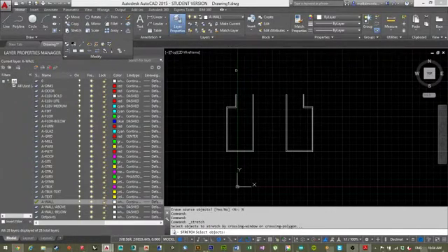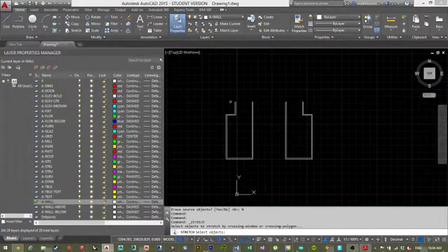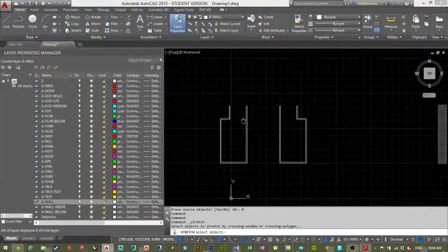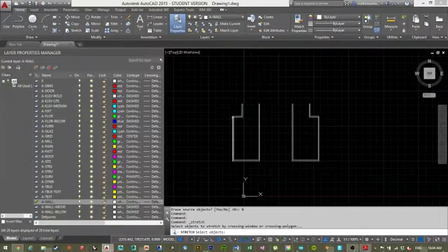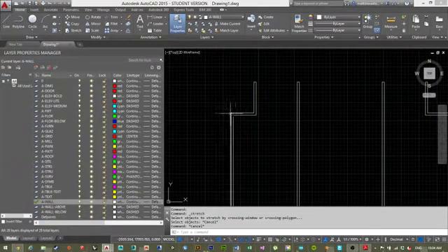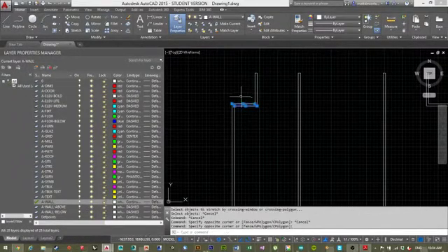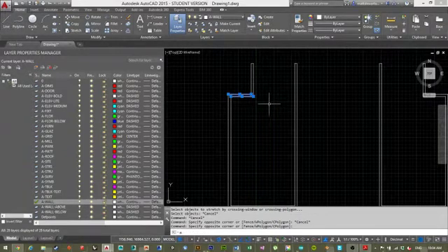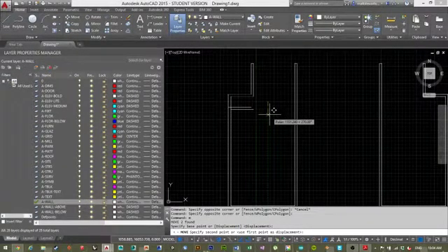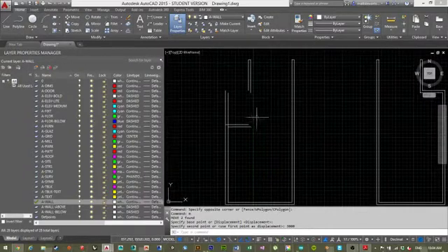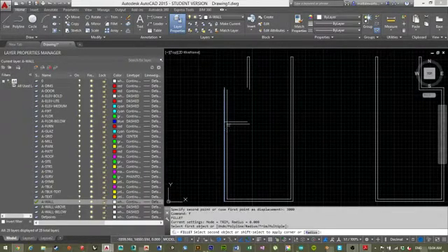So stretch, I don't believe they have. Stretch is probably the command I use the most that I don't think Rhino has. So if I wanted to, say, move this wall down 3 meters, and keep the same shape, I could either take this and move. So I'm just clicking M, 3,000, and then fillet this.